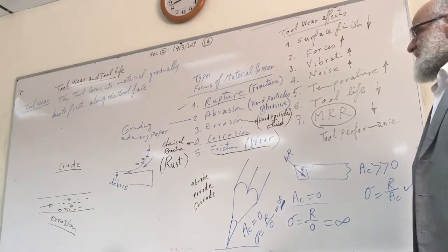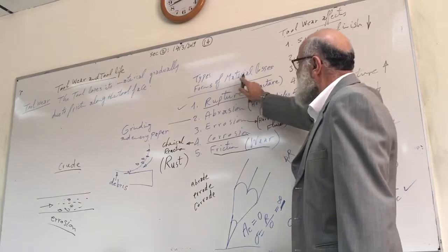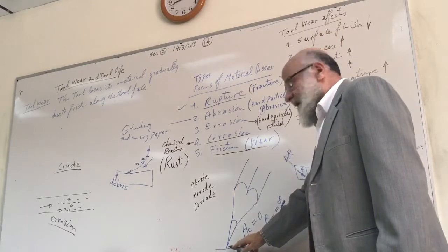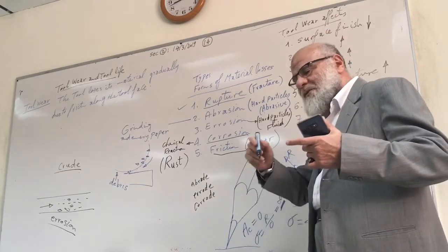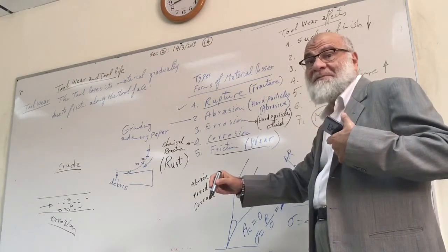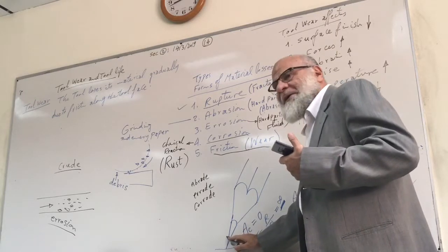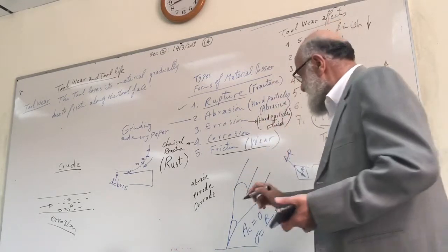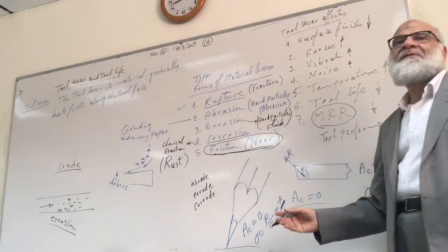Friction or wear. Wear is what? Material loss due to friction. Look here. After forming the area, what will happen? The pencil will wear out with time, and I benefit from this time. I benefit from writing until it gives me a big area, then I sharpen it again. Right? So the benefit time is this one: gradual, universal wear that takes time, and it is the beneficial one.